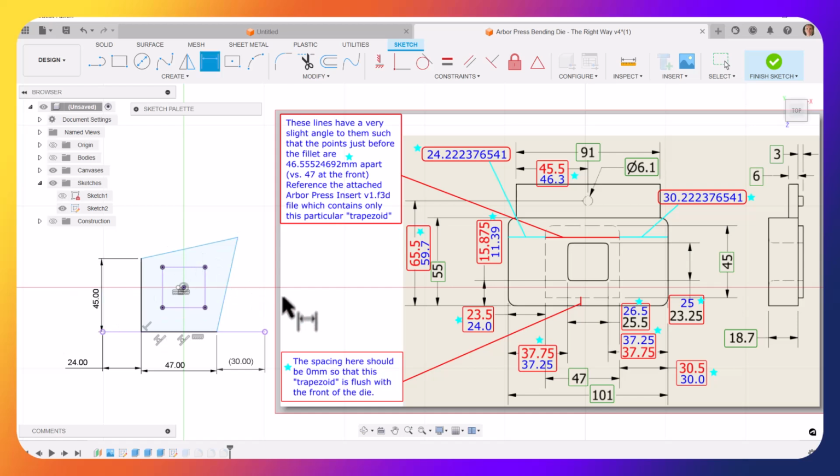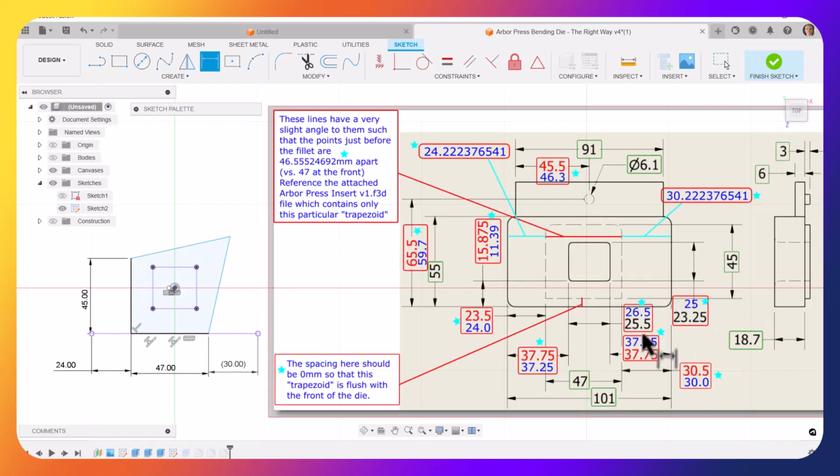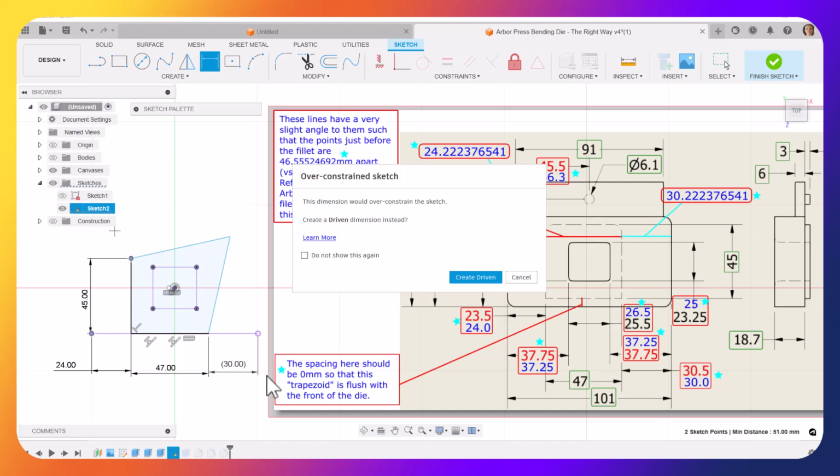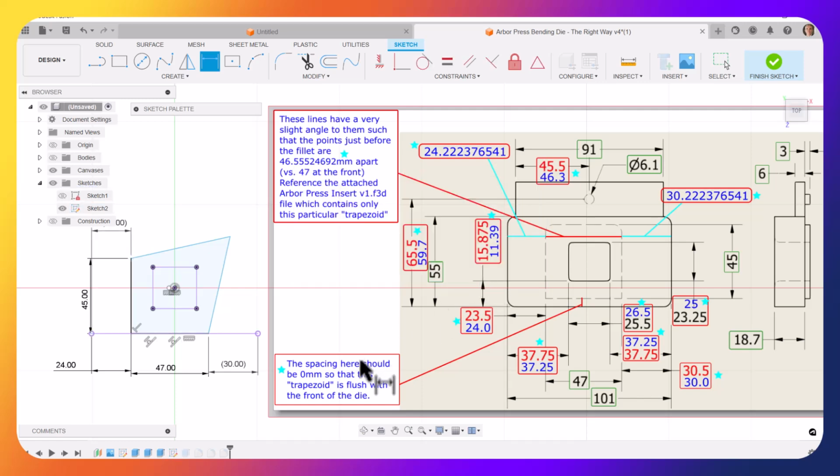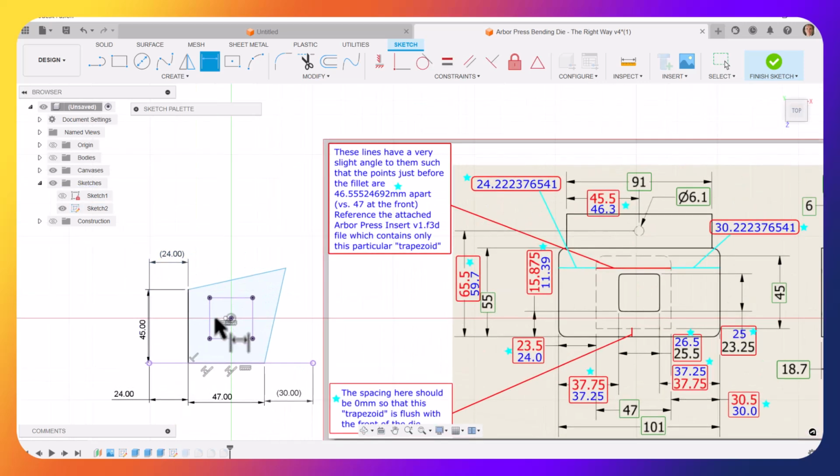And then let's see what we have then. This dimension from here over to here. And so I'll dimension that. Now I could type in, so that one actually is, let's go ahead and create that. And so I actually need to change that so that it isn't perpendicular. And so I'm going to undo that. And we'll get rid of that perpendicular constraint, and then we'll put in that dimension from here to this corner. And so the new intention is this dimension right here, 24.